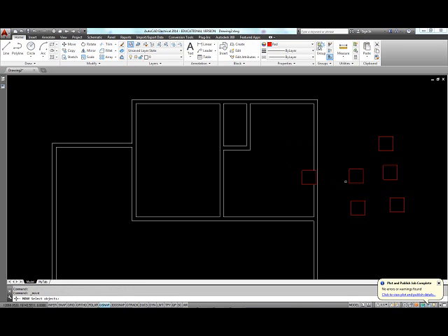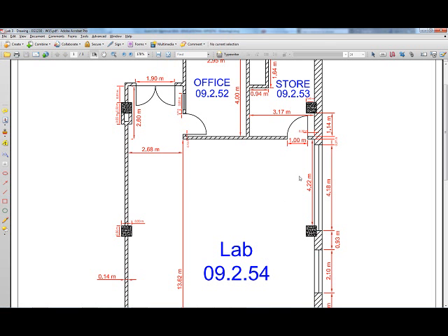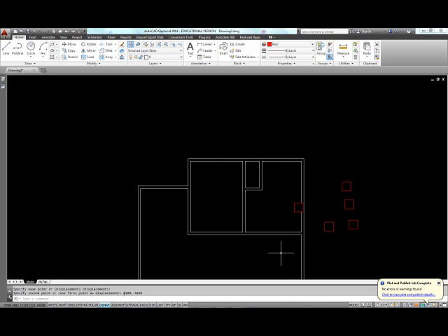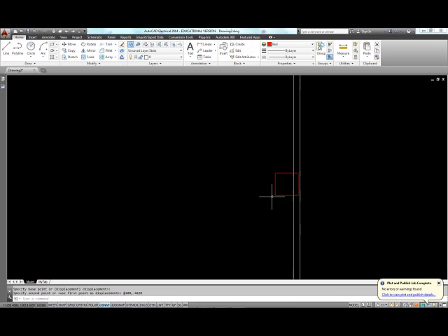Let's move another one, this time from the upper right corner to this corner, and I need to go to the right by 100 and down by 4220. So move this object from this corner at 100 comma minus 4220, enter, and you can see that it has been located properly. So trim using this as edges, spacebar, and choose this to trim it.